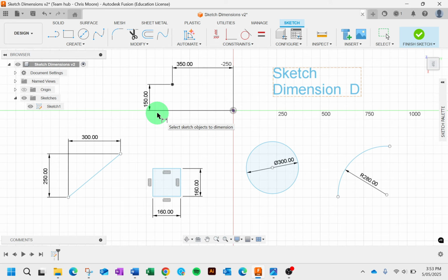Updating your design, you'll often need to adjust dimensions after test prints to improve the fit. Also, keep dimensions clearly organized. So small dimensions closest to the objects and large dimensions further out. Align dimensions neatly to avoid confusion. So clear and accurate dimensions help avoid errors and ensure 3D models work when manufactured.